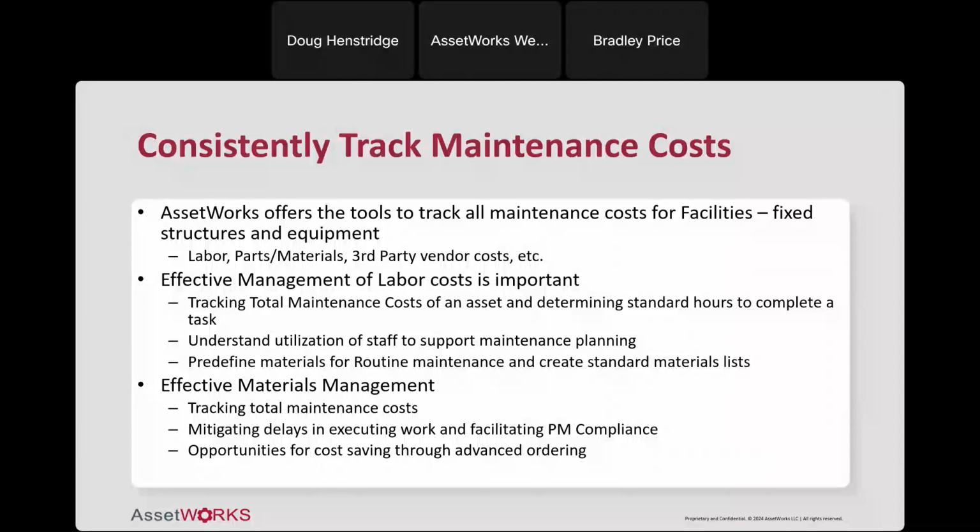And the other thing this gives you is data to create job estimates, so that you can predefine from a planning point of view that if we're going to do this quarterly inspection, that's going to take us an hour, and we have 20 of these pieces of equipment. So every quarter we have to plan for 20 hours to do this inspection. And when you set your schedule to come up on an incremental basis, you can spread those 20 hours out, and maybe say that, hey, every other Monday we're going to do X number of these throughout the quarter, and put them on a schedule that way.